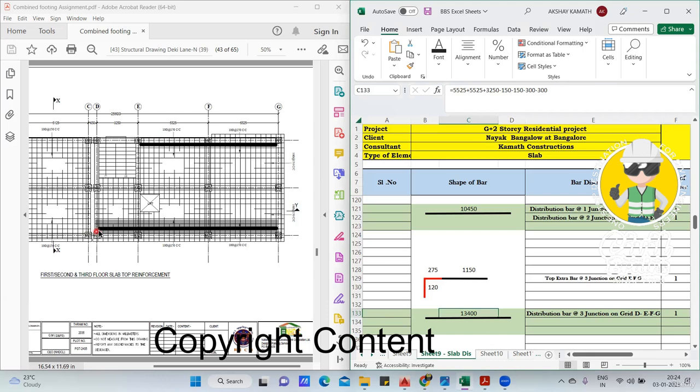13.400. If you're putting a bar from here to here, in spite of cutting also, your cutting length will be 13.40, which means it has gone beyond 12 meter. So lap has to be provided. So practically, if you ask me, usually lap won't come since it's a distribution bar. I told you practical on the site, it has to be something like this, isn't it?